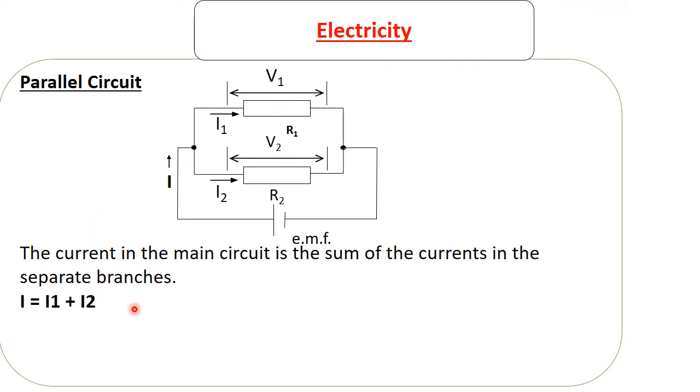What about voltage? For voltage, it is opposite to current. This provides the voltage. Is that voltage divided between the two cells? No. Voltage is like the forces between 2 points. Remember the meaning of potential difference, the difference in potentials between 2 points. If you look at this component and this component, they are both connected to here and here. So the potential difference between here and here should be the same.